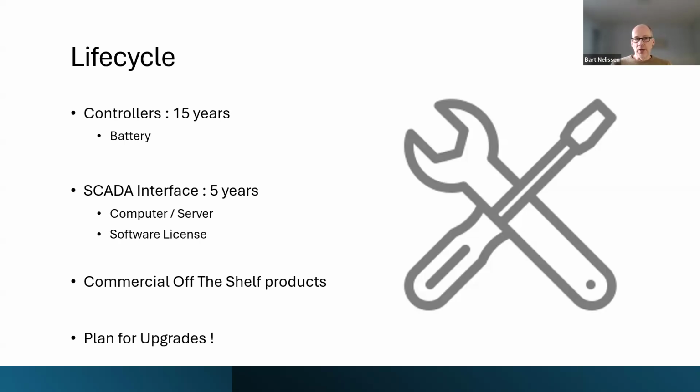The software license for a SCADA product can often be purchased with a support agreement, which allows the users to stay current with the product. And we certainly recommend that. At the end of the day, we urge our users to maintain a common off-the-shelf product, to not generate a unique solution. So as far as life cycle is concerned, highly recommend to plan for upgrades, no matter what stage you're in.